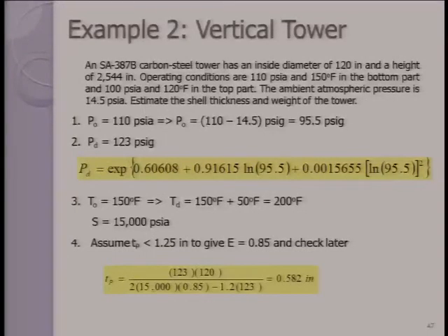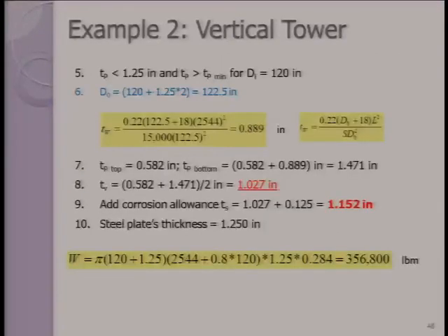So we're going to do the same calculation. The only difference is with the wind load. Yeah, so I'm not going to go through the same part, right? We know how to do it. So now let's go to the wind load. Okay? So the only difference is here, starting from 0.6, between horizontal and vertical. So like I said, the outer or external diameter is always calculated as DI plus 2.5 inches. So this is our number.